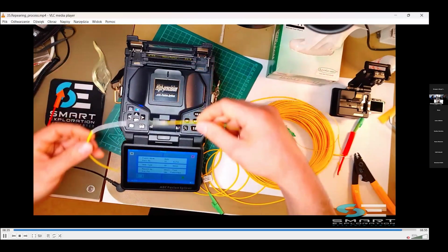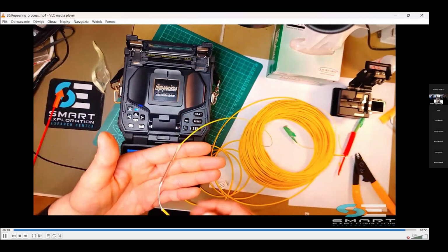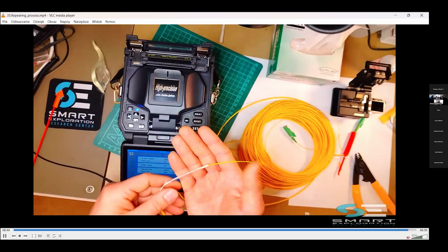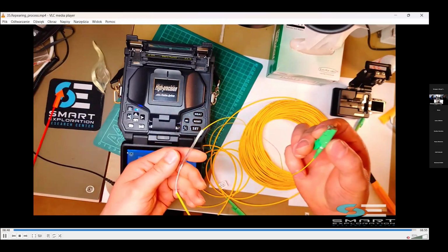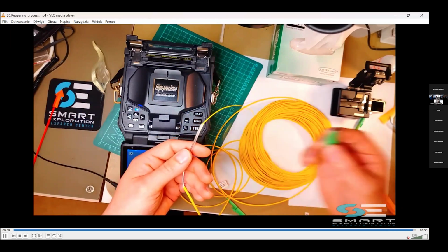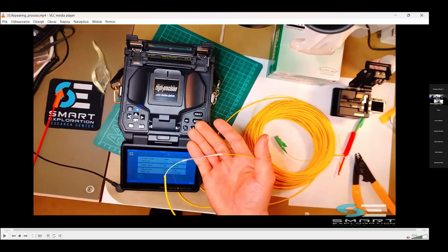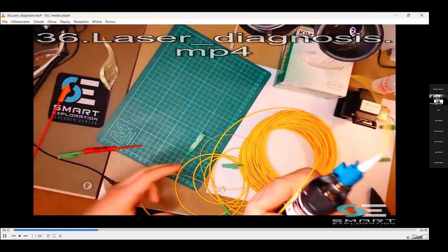After heating, we have a proper connection. That connection we can protect with some insulation. Additionally, we can add some additional shrinkable tube to make it stronger.